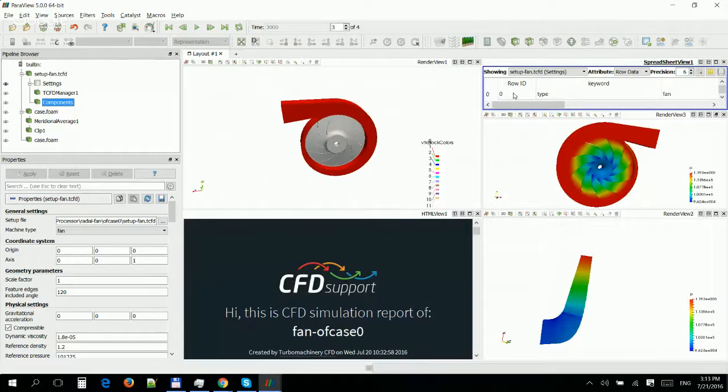So there is always the configuration file and the surface geometry. When starting a new simulation, you can write your configuration file from scratch, or the most effective way is to modify an existing tutorial case to the case you want to simulate. You can just replace the geometry and modify the settings, and you can go.